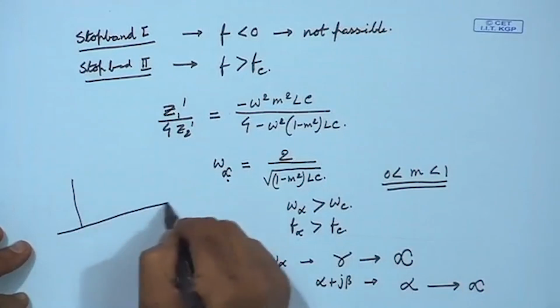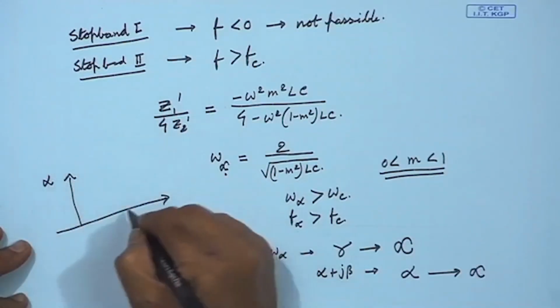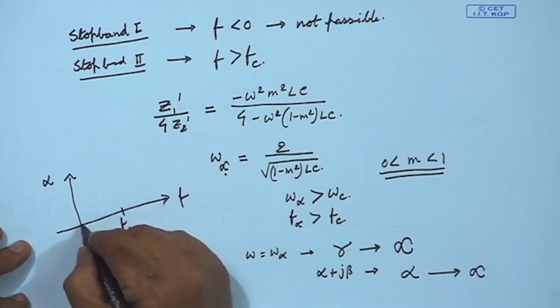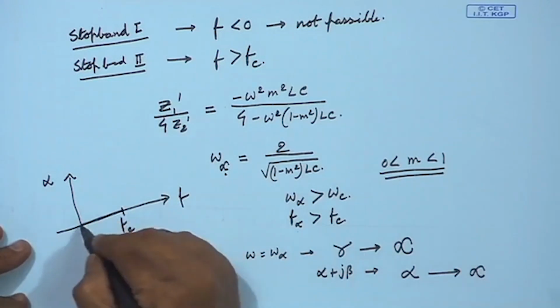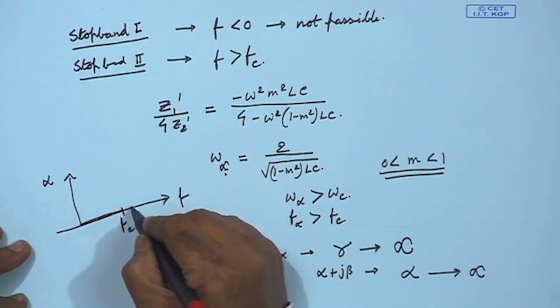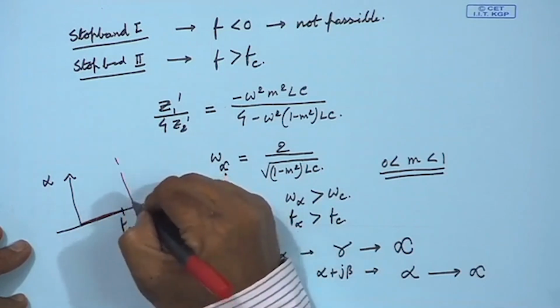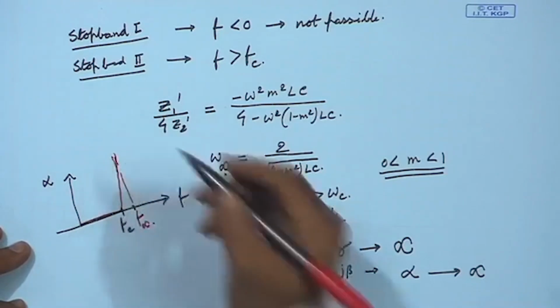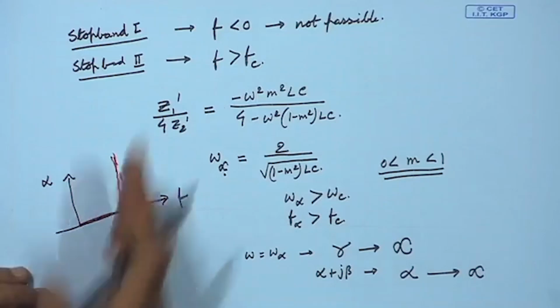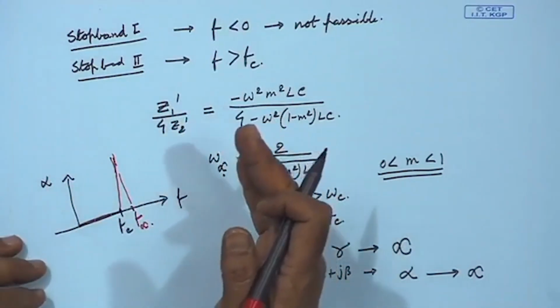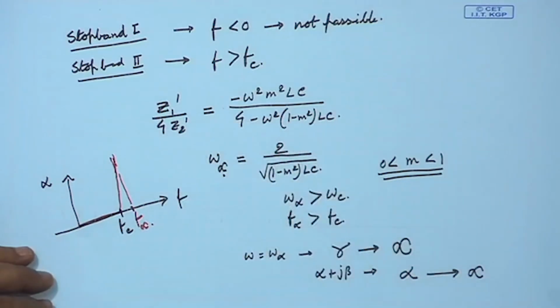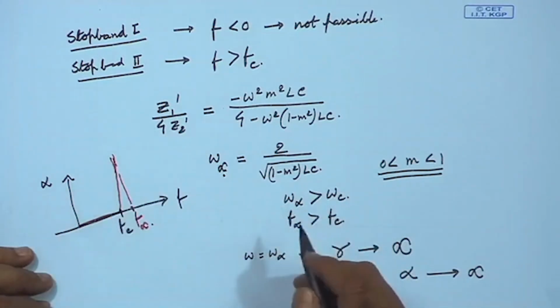Okay, the attenuation constant graph alpha, this is f c. Suppose I put f infinity here, then obviously the curve will come like this, but then I have a choice that I can force the curve to go like this asymptotically. So, I can give a very high attenuation just when I enter the stop band, which was desirable, because many applications say that do not disturb your neighboring channel. So, there I can put sufficiently high attenuation.